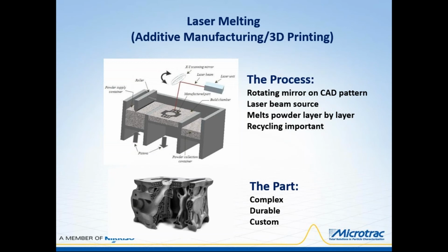All particles not melted onto the part are scraped off while the next layer is loaded. Attempts are made to successfully reuse the unmelted particles for as many cycles as possible before they show too much wear to meet size and shape criteria. It can take 10 pounds of a metal powder to produce a 1-pound part if the left behind powder can't be recycled.